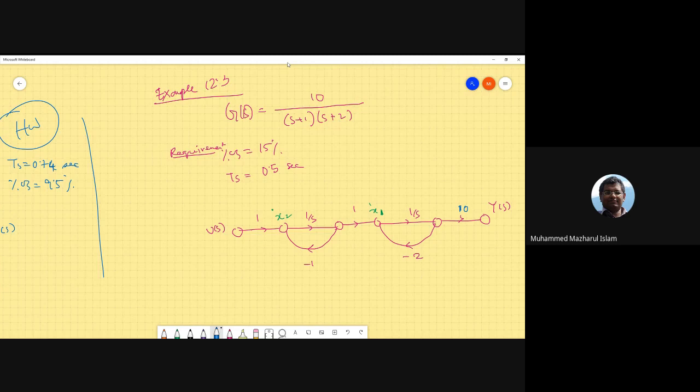This is a cascade controller. Now again, this is controllable, as you can understand that u(t) controls x2 dot, and x1 dot is dependent on x2. See, this is x2, and this is x1. So in effect, u(t) also controls x1. So this should be controllable.